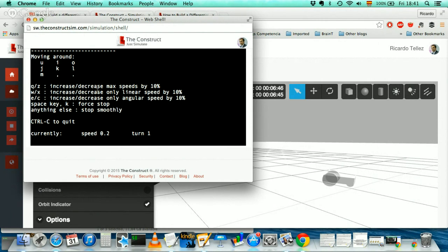And this is the end of the webinar. I have shown you how to build a basic differential drive robot, how to attach some joints to this robot, and make them revolute by using a plugin that accepts ROS commands. I have also included here some files that you can use as a template for your own project, like the model or this keyboard launch file that will allow you to move and test your robots very easily in the simulations. And now, this is the end of the webinar.